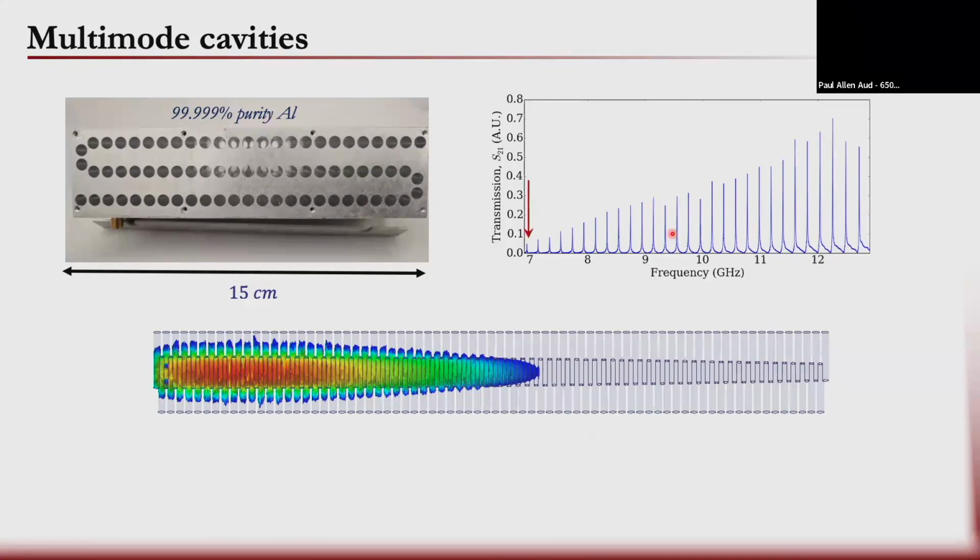We have this fun technique for how we make it. We call it a flute because it looks like Swiss cheese and you can see through it. But even without putting a cap on it, it should have a Q of over 1 billion in terms of radiation loss. It's made out of a solid block. The idea is you drill from the two sides, and where they overlap, there's a continuous waveguide. But to get out, there's only a small hole that's evanescent.